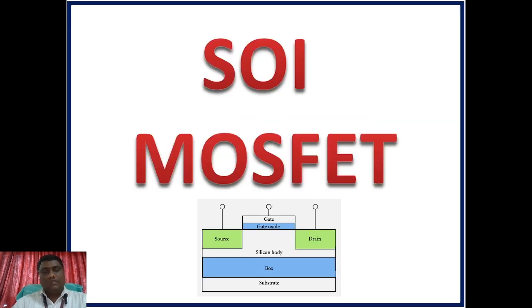So we will discuss what this SOI MOSFET is, why we need to use this SOI MOSFET in the current scenario, and what the meaning of SOI is. SOI is silicon on insulator, metal oxide semiconductor field effect transistor, and you can see the picture here. We have the BOX, which is the insulator between the silicon body and the substrate.